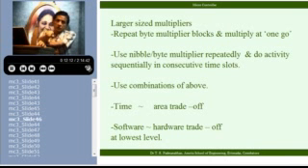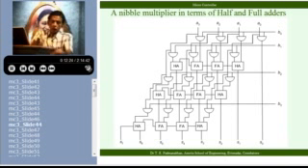In one approach, suppose I take a 16-bit by 16-bit multiplier. I can just directly extend the circuit discussed earlier. I can expand it in this direction, put all the 16 bits, form all the 16 partial products, do the half adder, full adder chain and complete. At one go, I will do a multiplication.